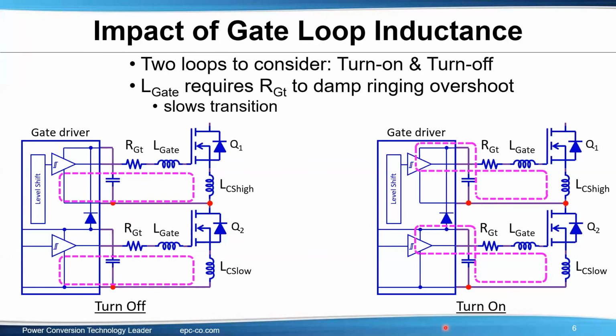How do you measure the VGS and VDS when you use a very compact layout? Black magic, very difficult to do. For VGS especially, what we usually recommend is using high bandwidth isolated optical probes. Depending on the frequency, it's difficult because with a specific layout, whatever you do, you're going to slightly change the capacitance or inductance of the loop.